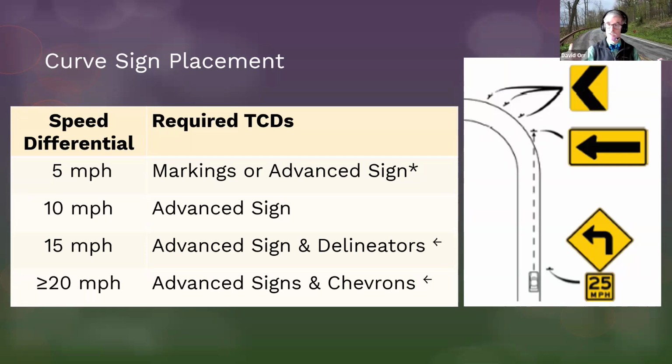Now, if people were going slower, even if the speed limit were 55, but they're actually only going about 45, you might be able to have less required traffic control devices using an 85th percentile approach. But remember, people might be going faster as well. And so consistency matters. So I'm going to ask you to raise your hand.